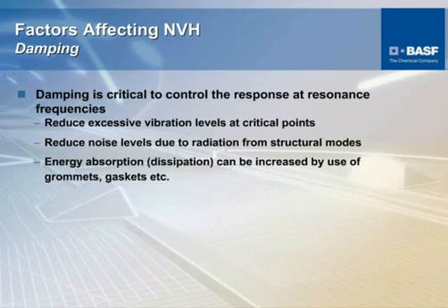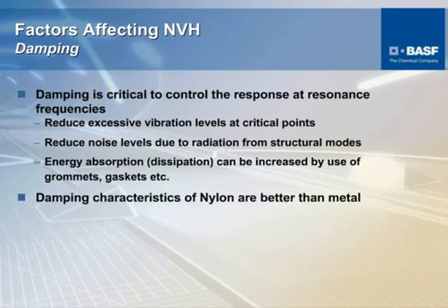Typically here, we're talking about materials and plastic materials, specifically nylon. The damping characteristics of nylon are better than metal, and that is a fact. You can actually take a piece of metal and take its equivalent in nylon just by tapping on the surface of that component. With both materials, you'll see the difference in sound level emanating from either component.